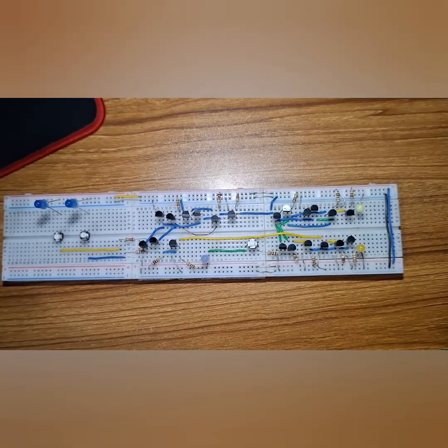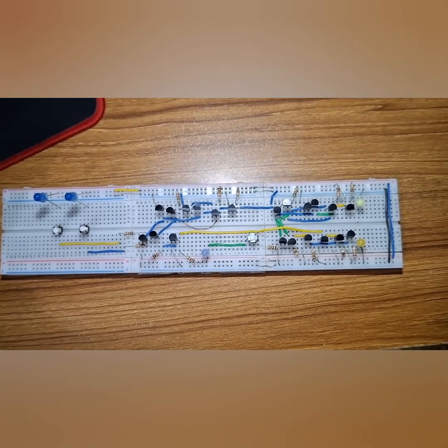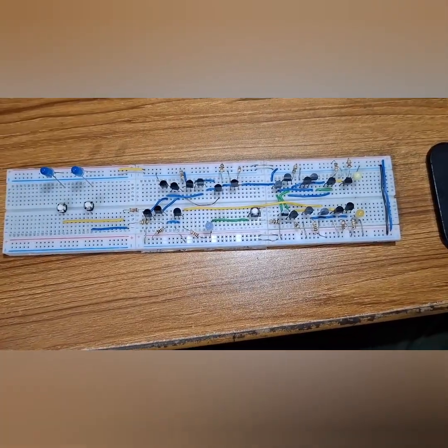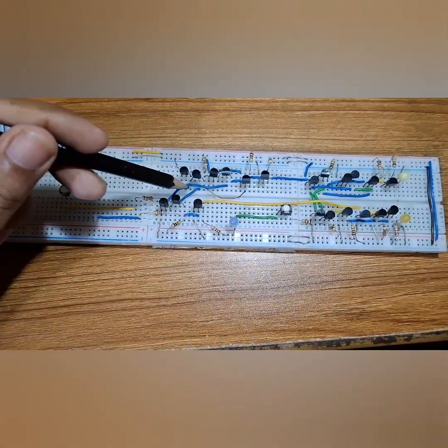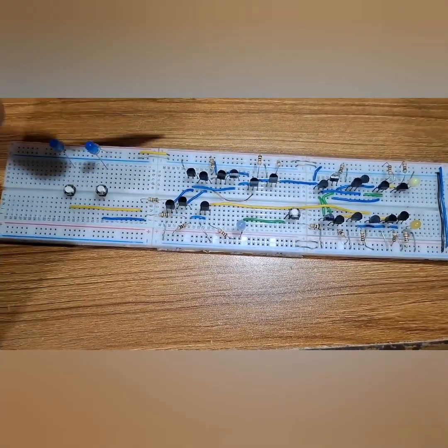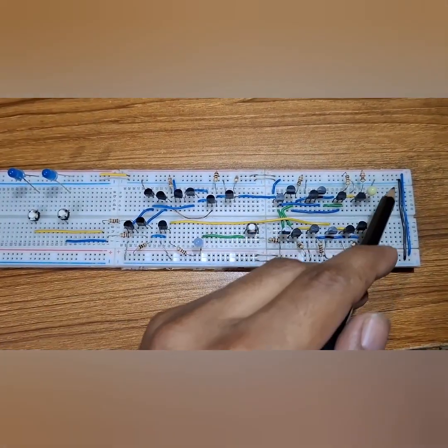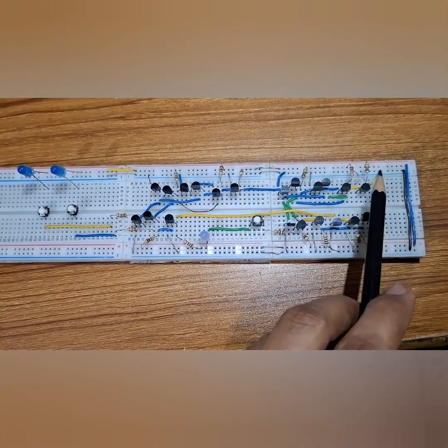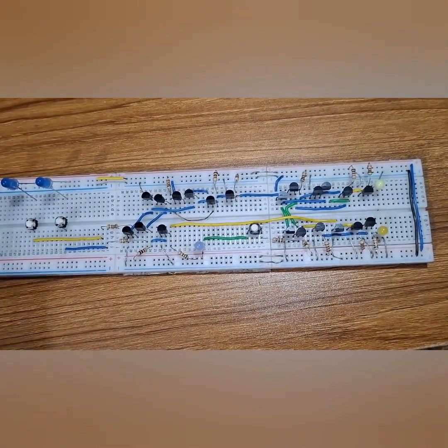So this is the connection we have given in our circuit on the breadboard, as we saw in our circuit diagram, implemented here. If we look here, we will find the first XOR gate. This is the part where we have designed the first XOR gate, 1 2 3 4 5 6 transistors. This is the second XOR gate, where we also used 6 transistors, and we have taken the summation output here from this LED and the last transistor of this XOR gate.